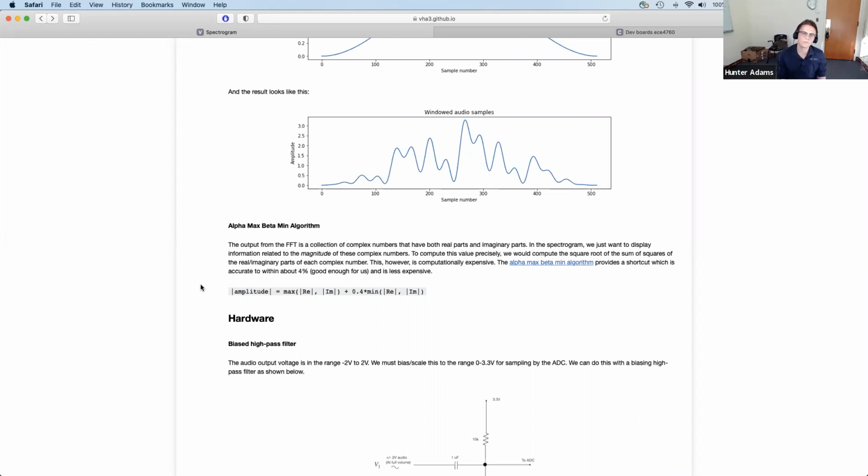So keep in mind, the input to the FFT is the real part of the signal and the imaginary part of the signal. And the output of the FFT has both a real and imaginary component to it. So you're putting two arrays in and you're getting two arrays out, and both of those arrays are the same length. So let me try this. You're expanding the one-dimensional input signal into 2 dimensions so you can more easily understand it.